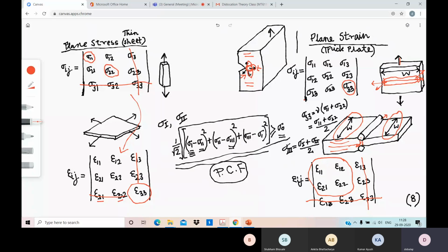But have an understanding of these two aspects, because plane strain basically introduces stress along the 2 other directions by resisting the strain along those 2 directions, and increases the yield strength of the material following von Mises criteria or even Tresca's criteria if you consider.